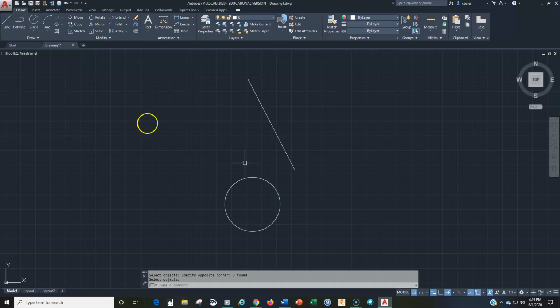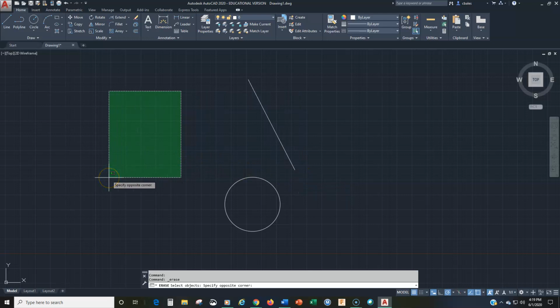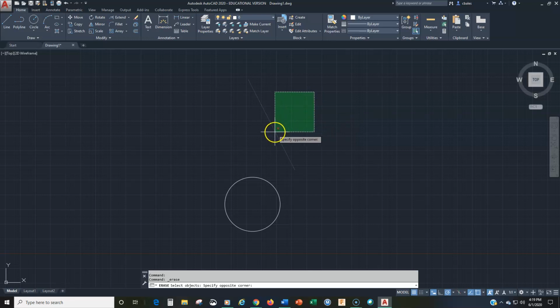All right. Now, there's another implied window. So we go back to the erase command, and remember, we pick out in space and we drag it to the right, we get the blue window, selection window. If we drag it to the left, we get the green crossing window. And let me position this a little bit better. The green crossing window is different because, now watch, I don't need to get things entirely within the window. All I need to do is cross the window.